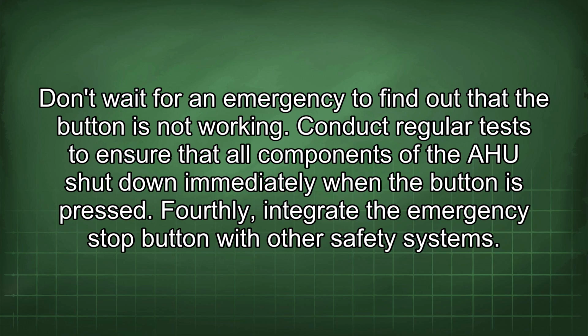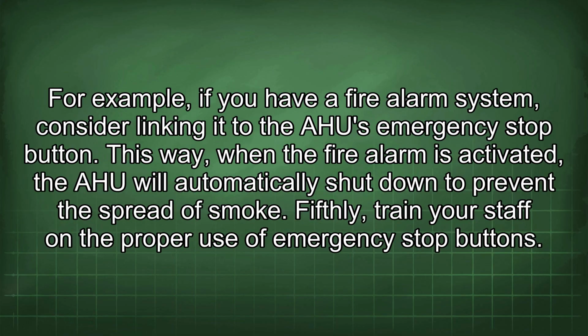Fourthly, integrate the emergency stop button with other safety systems. For example, if you have a fire alarm system, consider linking it to the AHU emergency stop button. This way, when the fire alarm is activated, the AHU will automatically shut down to prevent the spread of smoke.